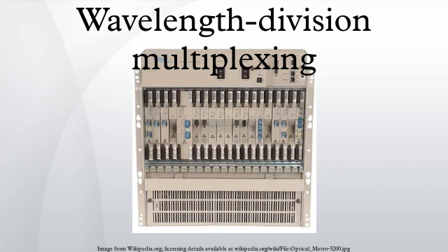WDM systems. A WDM system uses a multiplexer at the transmitter to join the signals together, and a demultiplexer at the receiver to split them apart. With the right type of fiber, it is possible to have a device that does both simultaneously, and can function as an optical add-drop multiplexer. The optical filtering devices used have conventionally been etalons.